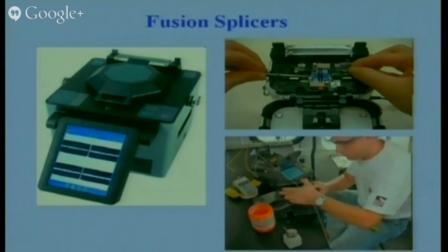All viewing is there. So when you close the cover, you will see everything come on the monitor. The monitor will check the cut in the fiber, it will check the alignment, both X and Y alignment. Once the fiber ends are fine, then the joint will be made and the arc will stop.